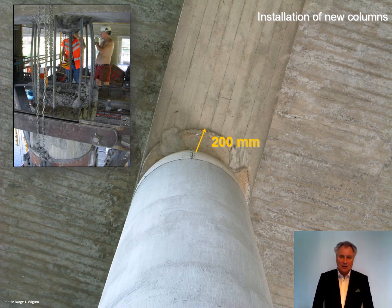So if you are walking under the bridge today, you can see the original place of the columns, and that they have been moved and refixed again 200 millimeters or 20 centimeters from the original position. But of course during the next 50 years or so, the bridge will still continue to expand, and then maybe after some decades they need to redo this rehabilitation and repair again.